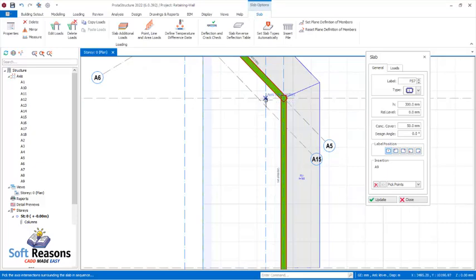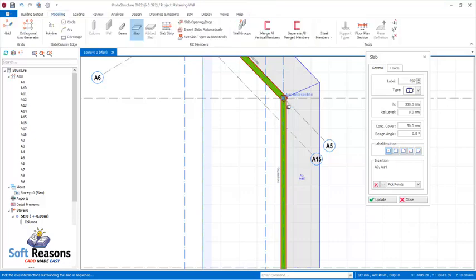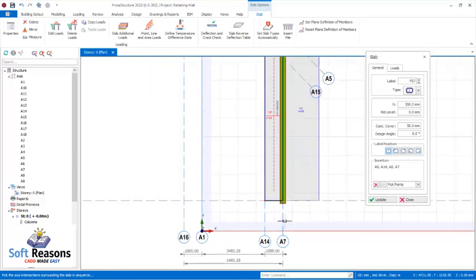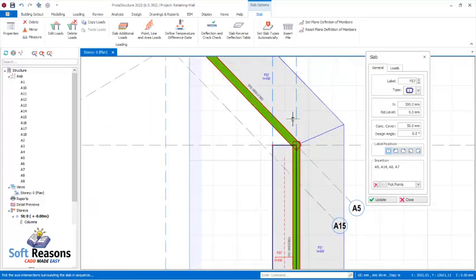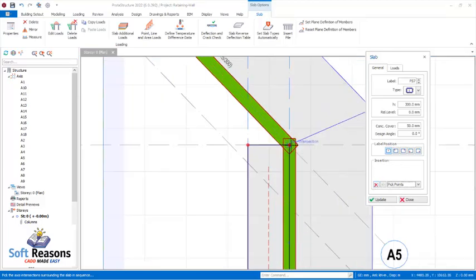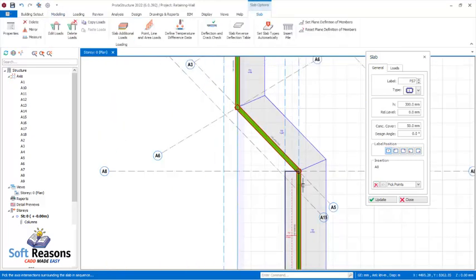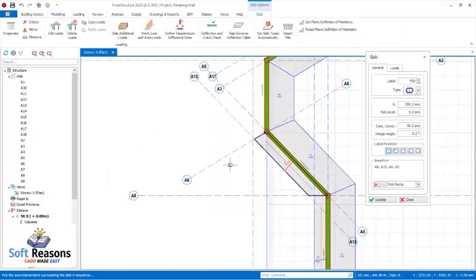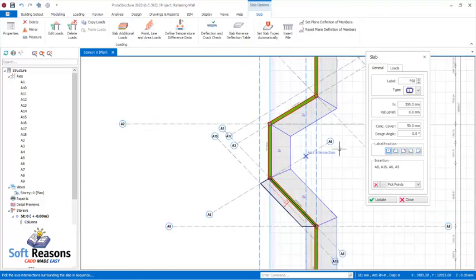I believe okay, so we pick here to be another point. Okay, so we all the way pick this place, so to have the slab being inserted just like this. You can see. All right, so after which we proceed by getting rid of the existing point using these options. So you pick another point to continue with the slab insertions. So this is how you are able to insert slabs successfully at the base of this type and geometry